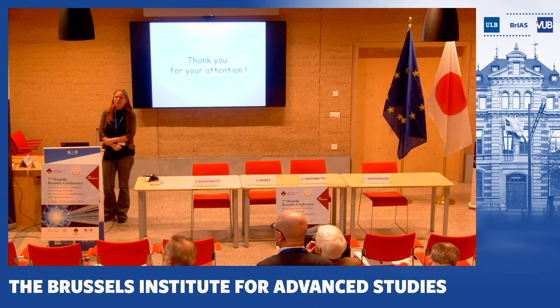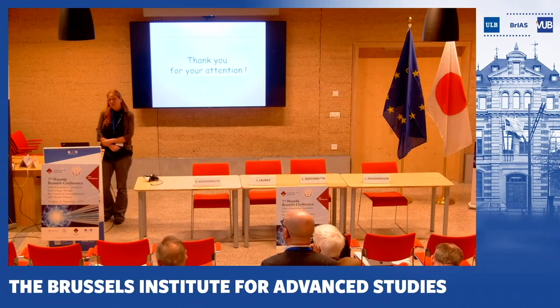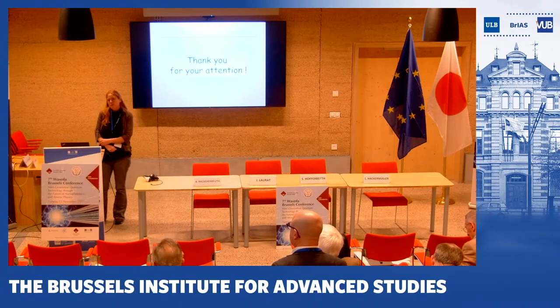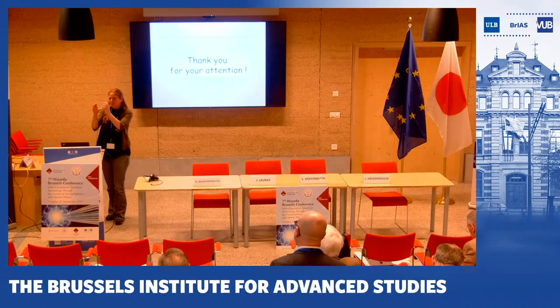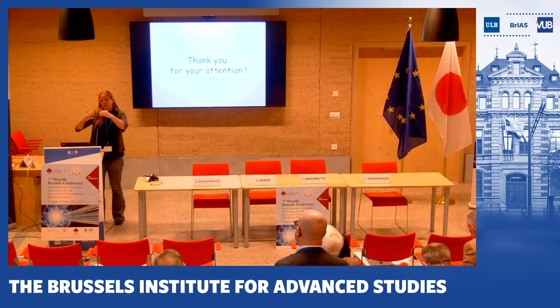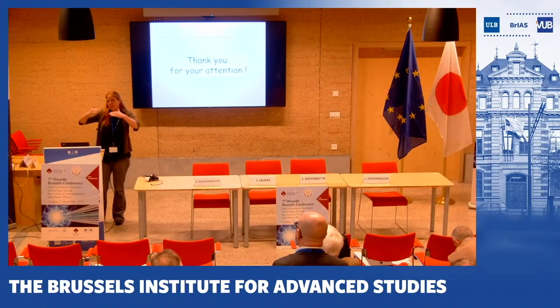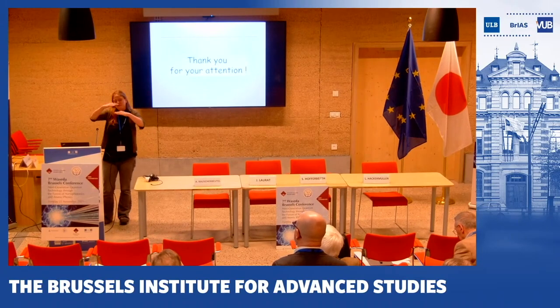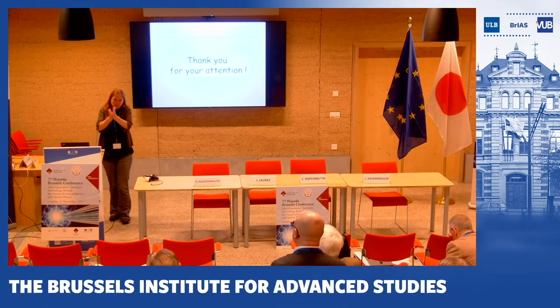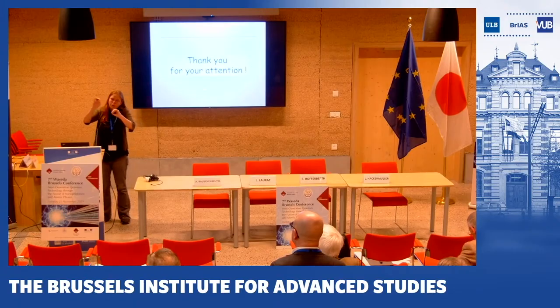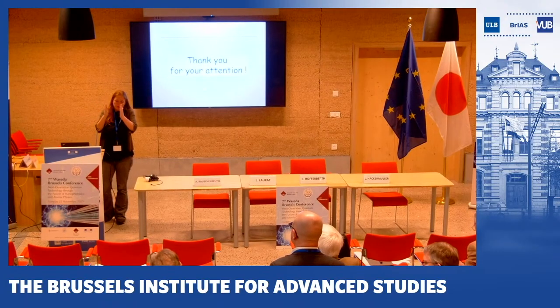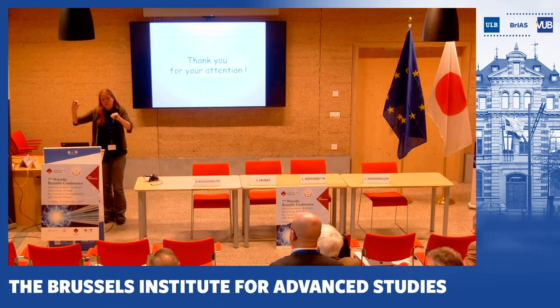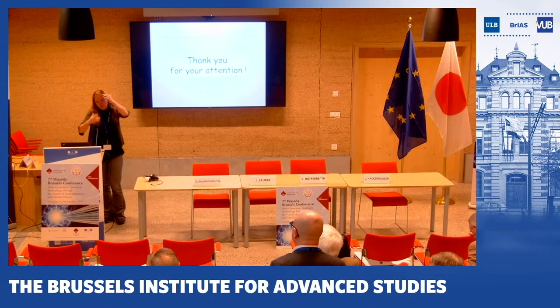Yes. We also did some simulations on that a while ago. As I said, we started with a round hole because it's the first thing that we tried. Also geometrically, that is challenging because the fiber, not for you because you do extreme things, is 100 microns and you take 30 microns out. But a round hole leads to a diverging beam, and the core is small. So the gap is huge for our photons. That's between 20 and 30 microns, and the core is just 5 microns. So we have to get them back into this core.